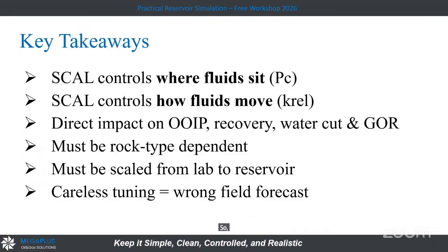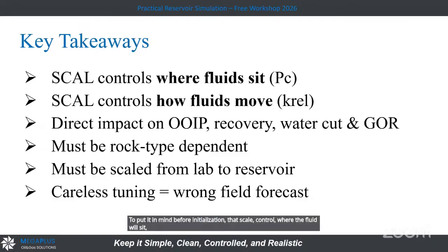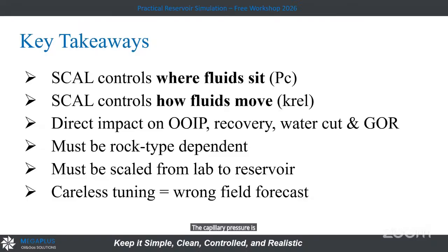So finally, some key takeaways that you have to keep in mind before initialization: scale controls where the fluid will sit. Capillary pressure is the distribution of saturation. Relative permeability is how the fluid will move. How the fluid will sit is capillary pressure; how it will move is relative permeability.